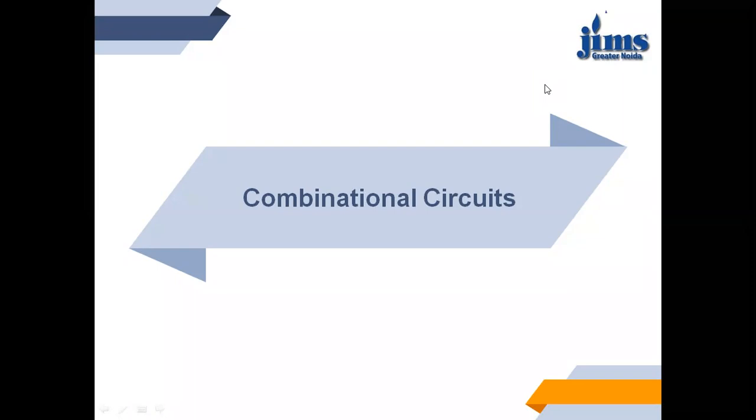By using these properties, we can reduce the Boolean expression. Another one was the Karnaugh map. With the help of the Karnaugh map, we can minimize SOP or POS, which are represented in the standard form, to the minimal SOP or POS form. And in the last lecture yesterday, we studied the tabulation method. That was the Quine-McCluskey method, which is an algorithm-based method used when the number of input variables is more than 5.